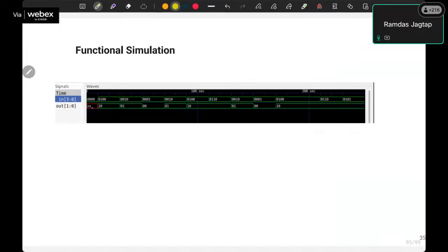So it is not decidable which bit to give the priority to, so it is unknown. And if you see the second column, there is 0 1 0 0, that is nothing but the 4, this particular column. So the priority is given to that particular highest bit. Similarly, you can see these things over here as well. In this case, the input is 110, but priority is given to the highest bit. Similarly, for this as well, so this priority is given to the lowest bit. Similarly, you can see over here as well. So it is 101, but the priority is given to that highest bit.